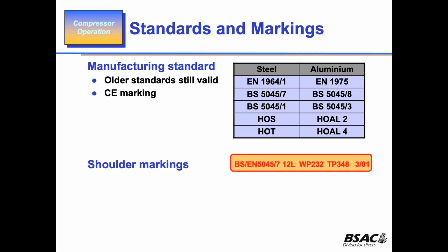And they're most important, right? They're most important that they are on that cylinder. There'd be a lot of other bits and pieces like the serial numbers, etc., but they're the most important part of it. Working pressure, that's the limit that you can charge that cylinder to, right? And the test pressure, you should never go anywhere near, right?